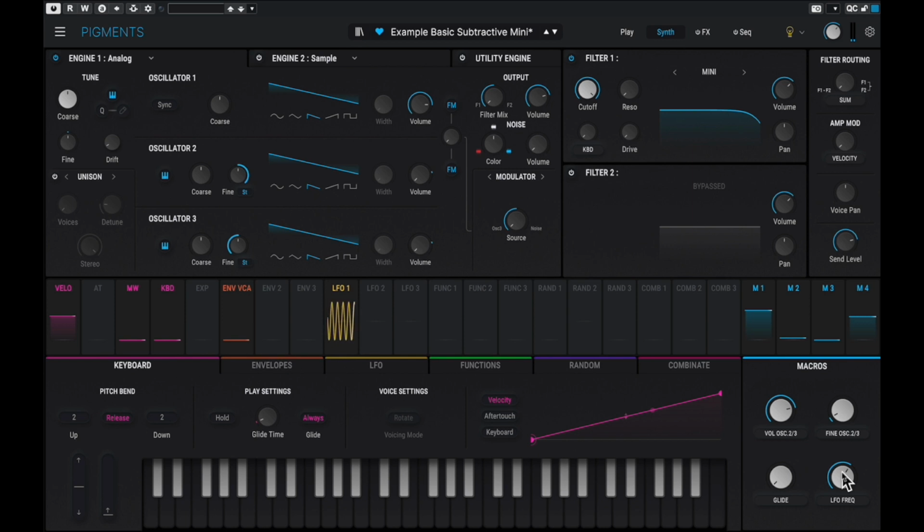Similarly, we could modulate the volume and get a tremolo effect, or modulate the cutoff frequency of a low-pass filter with some resonance to get some wah-wah effect, etc. The wah-wah effect is just a change in the cutoff frequency using the resonance of the filter.